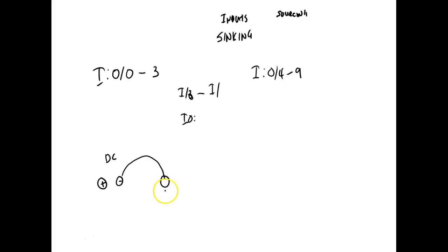And they don't say ground, they say DC. It's called DC-COM. That's what common is. And then over here, the other set, I've got a jumper that's going to jump over here to its what? DC common. But you don't have to hook up both sets syncing. You can hook up one sourcing if you want to. You decide what you're going to use for common. Everybody understand that? Yes or no? Okay.